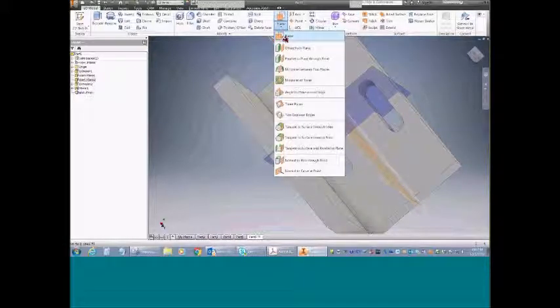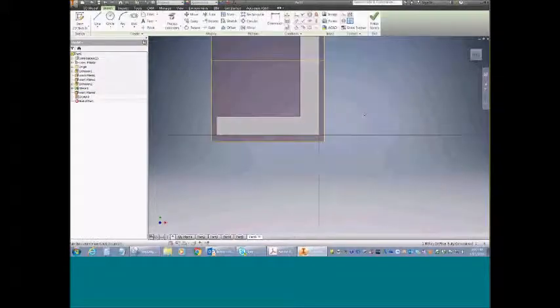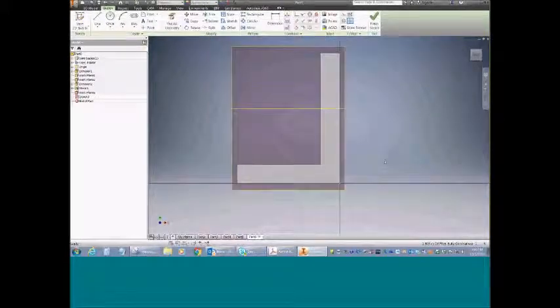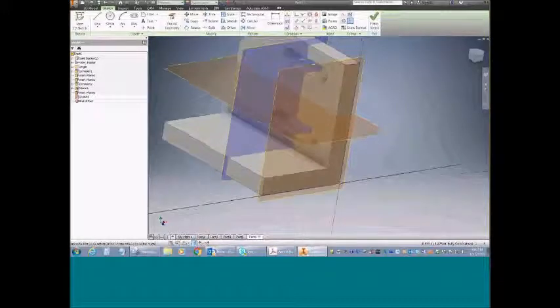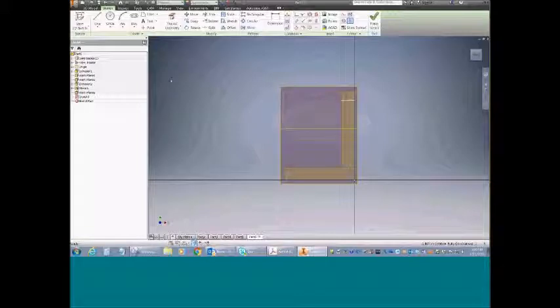So this gives us the opportunity to talk about an offset plane. So we would talk about that. I'm going to offset that plane for my supporting rib, and it looks like that should be negative 1.25. And so I'm going to do a new sketch on that plane. I'm going to cut back to that plane, so I've just visually removed the geometry that's sitting in front of that plane. It seems to make them a little more comfortable when they can see this has been cut away.